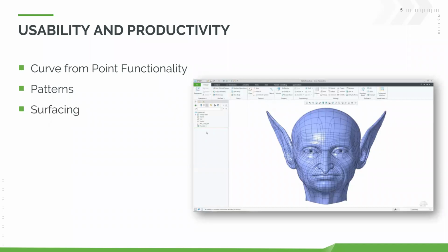Improvements here in surfacing. First and foremost, you have better control over the curve definition, specifically curvature and acceleration control points. You can now grab them, see them, which makes it easier to get those curves exactly the way you want. And you can see here also in our freestyle tool, we can now smooth and simplify curves. We have a new brush capability within that freestyle tool for really sculpting more of that organic shape. I'll go through and show what that looks like in a brief demonstration, but that's a very strong tool that we have now within freestyle. We also have the ability to mirror shapes inside of freestyle. So a lot of different additions in that area. And again, a tool that's actually available to all of our Creo users, even in the base package of Creo.